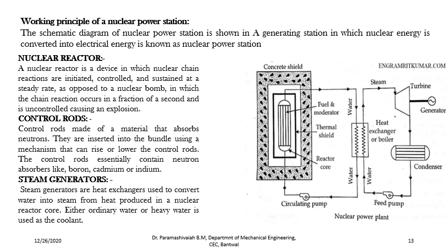Then the steam generator, as I told you, is the heat exchanger which exchanges the heat between heavy water and soft water. After absorbing the heat, this becomes steam, and high temperature, high pressure steam goes out. Then after losing the heat, low temperature heavy water comes again into the reactor. This is how it continues. I hope it is clear.